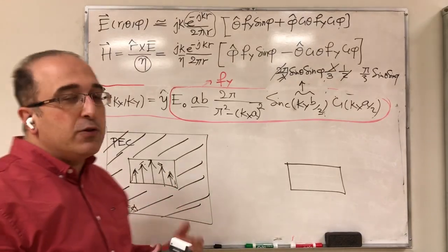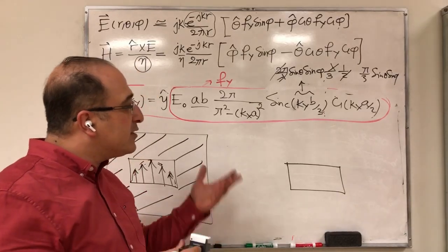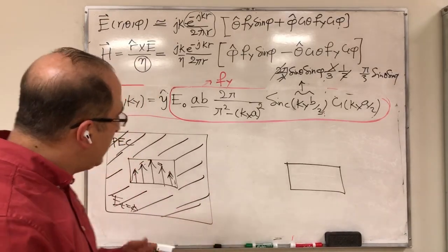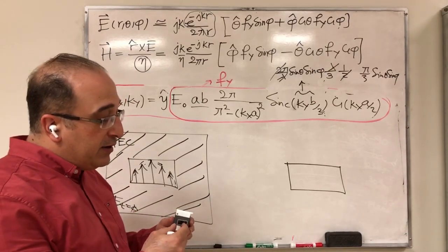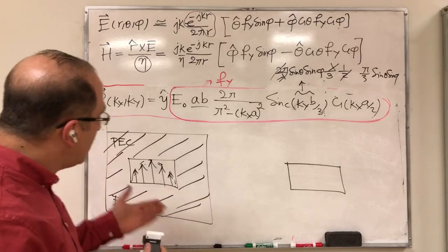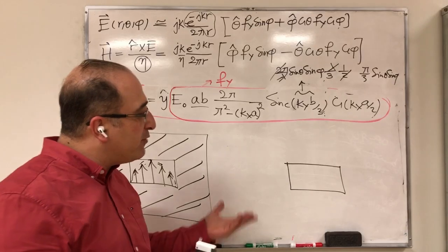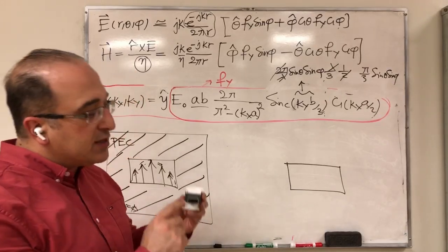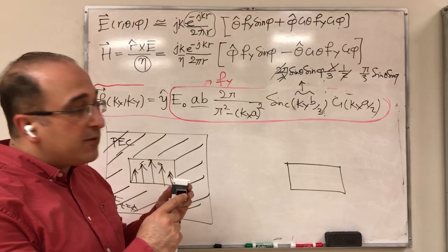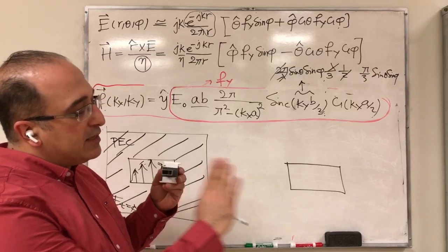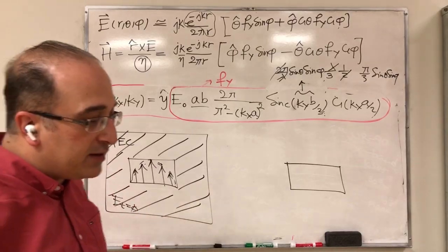Of course, that gives you a little bit of error, but in some situations this could be acceptable. But of course, that's not going to be exactly right, because we won't know the field exactly. The nice thing about the PEC plane is that we know the field exactly. But that's one way of thinking about it, to just assume that you have the cosine taper electric field here, and outside that, on the XY plane, the remaining field is 0.